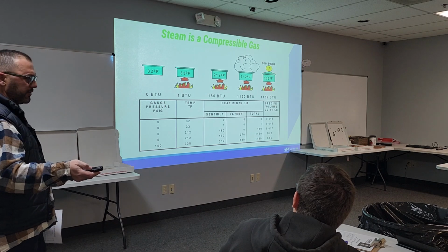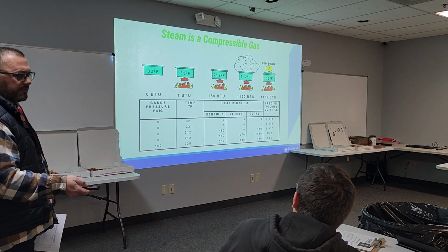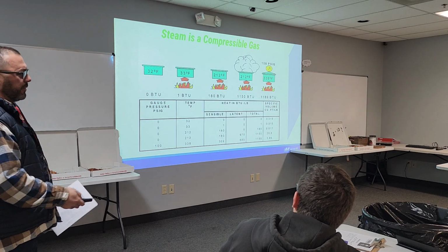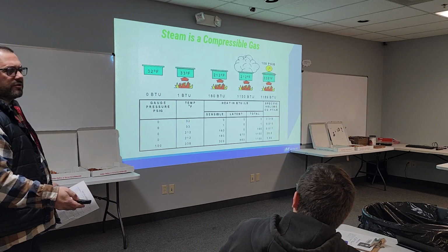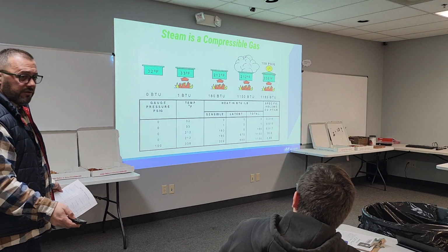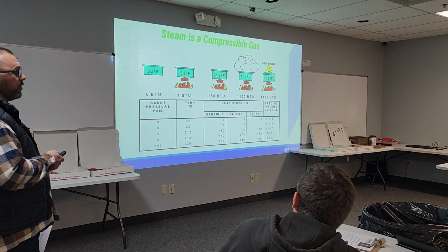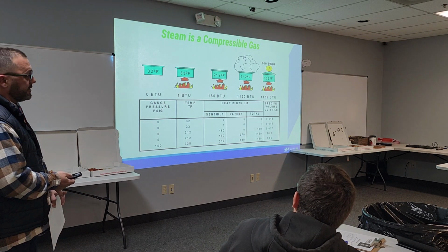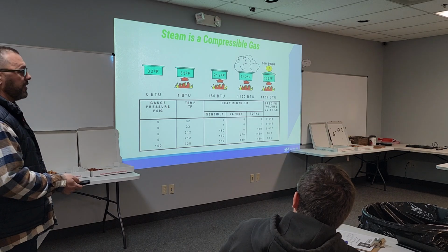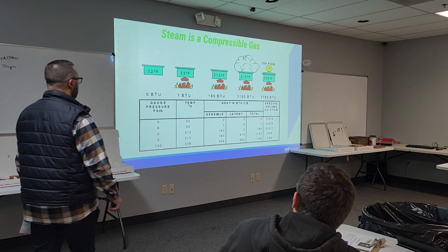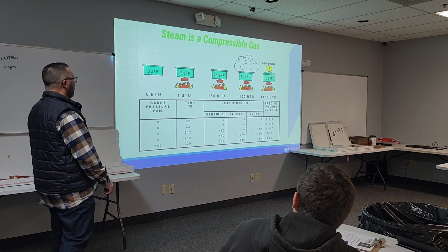So there's really four parts to a steam system. Generation, that's the boilers and steam generators. There's the distribution, that's the piping systems, which we want to be as small as they can be. We don't want to buy 16-inch pipe if we don't have to. Then there's utilization: our heat exchangers, jacketed kettles, autoclaves, all the different areas we're generating steam for.